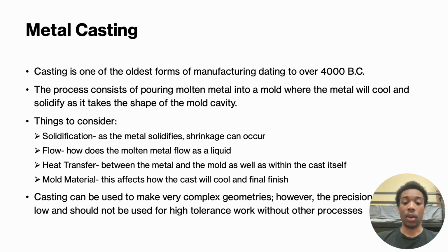You need to consider the flow of how the liquid metal behaves, right? When you're pouring that liquid into that mold, you don't want any air bubbles or gaps or anything that can mess up the final workpiece. Next, you consider the heat transfer, right? You're working at high temperatures, and the rate of heat transfer is going to affect how the material cools, right? You want it to cool a certain way so there's no cracks or anything, and the mold doesn't crack either. And then finally, the mold material.